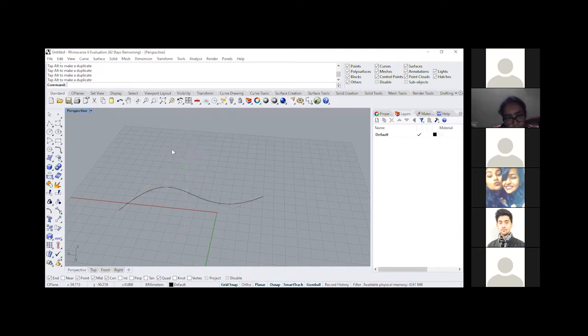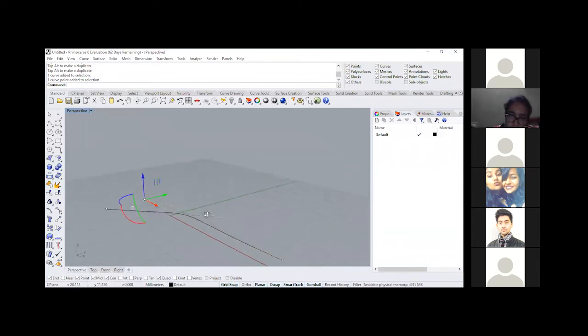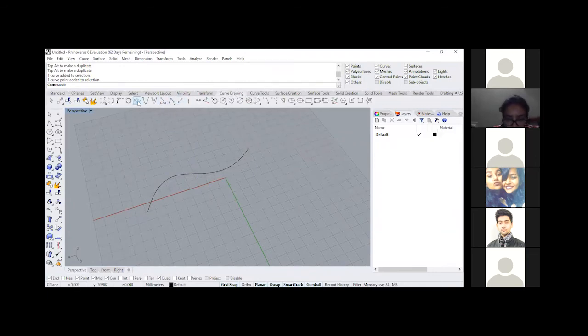Like I can click on the icon, like say for example, I'm selecting this single point, and I'm going to click on this arrow. I'm going to say 7 units towards the positive x, and it's going to take me 7 units towards the positive. Right? So that is a control point curve. Now let's go ahead to interpolate curve. That's the next icon that you're seeing over here, interpolate curve. Or in the standard toolbar also, you can go down over here and you can find the interpolate curve.